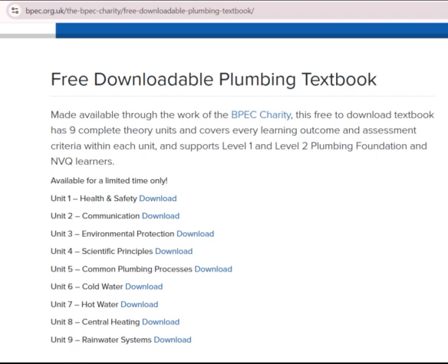In domestic dwellings, the main system used was the pumped heating with gravity hot water, semi-gravity system. The diagram shows a typical domestic pumped 1-pipe semi-gravity system. Here, the hot water storage cylinder heats up by gravity circulation, with the heating water to the radiators being pumped by a circulating pump installed on the return part of the pipework loop.